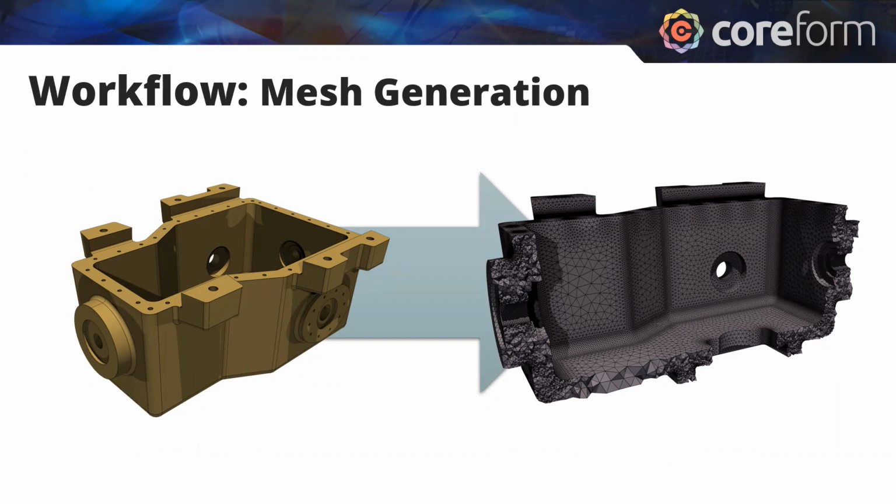And again, there's a whole bunch of strategies that we'll go into for maybe you want to do tet meshing, hex meshing, or a mixture thereof. Maybe you want to do shell elements. So you want to have a meshing tool that can then build for you the required discretizations.